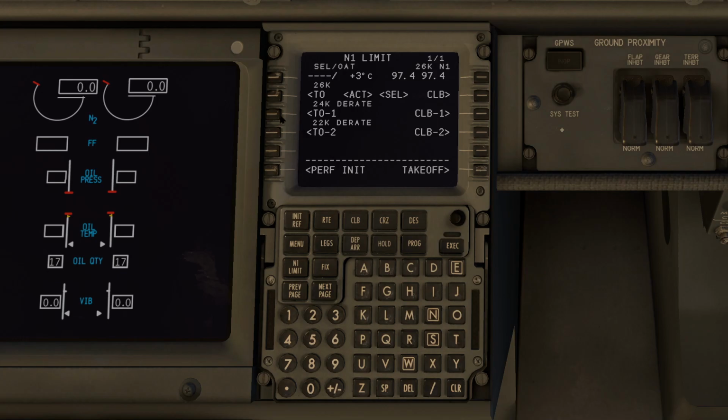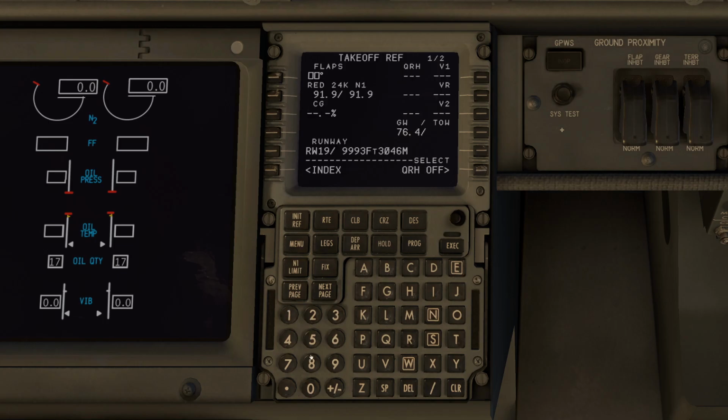And we are doing a derated takeoff with 33 degrees as assumed air temperature. Takeoff, we could use flaps 10, but let's see, flaps 5 is good enough. We will have a high V speed for rotation, 152. We will see how it goes.